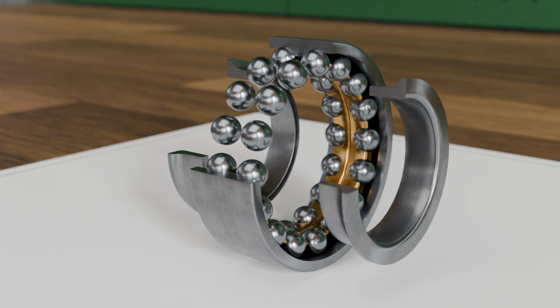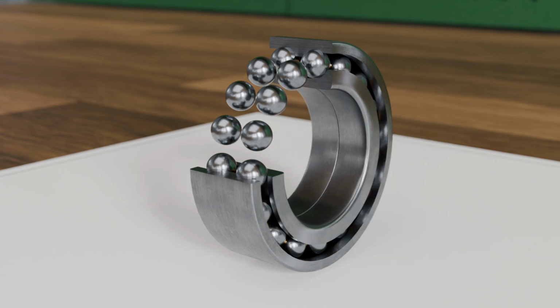First, all the balls are inserted together with the cage into the outer ring. Then, the two halves of the inner ring are slid in from both sides and joined together. This eliminates the assembly gap, allowing the bearing to be equipped with a higher number of balls, which increases its load capacity. Additionally, the guide tracks at the end faces of the inner ring can be reinforced or made taller since the inner ring does not need to be slid over the balls in this design. This allows for larger contact angles to be achieved, for example 45 degrees, which significantly increases the axial load capacity.